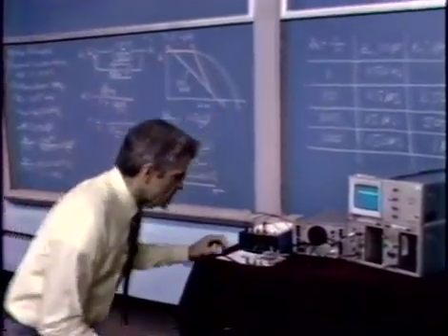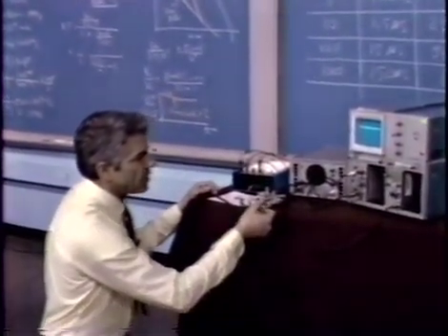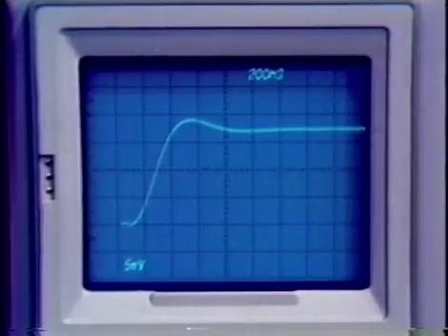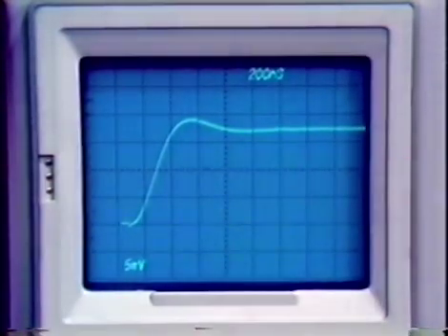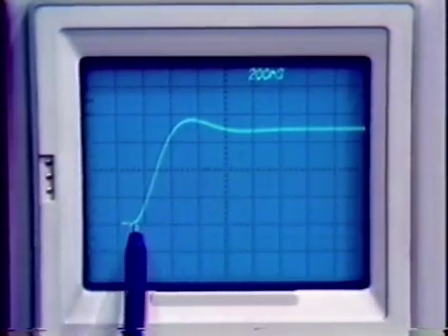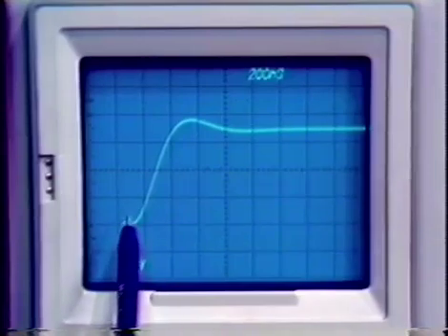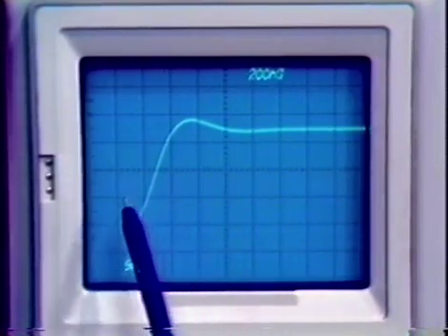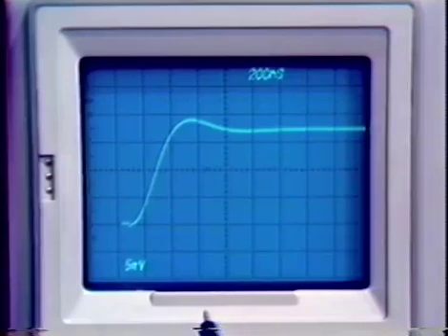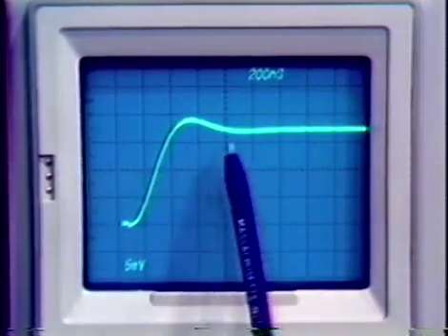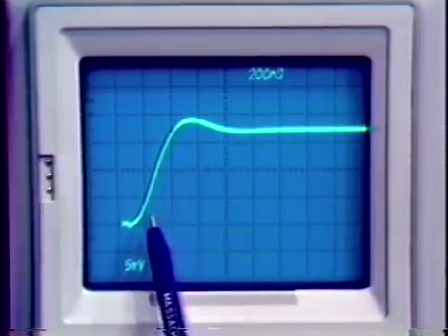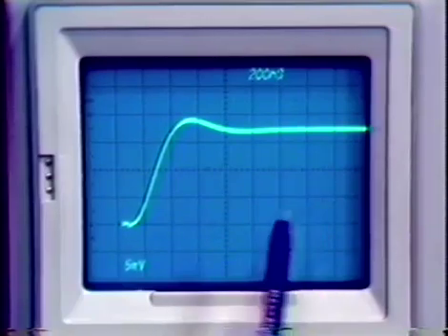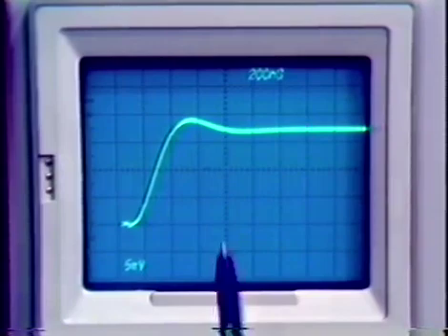We're first going to look at the small signal response of the amplifier. And let's look first at what happens with 1 over s compensation. Here we have removed the resistor in the T network, simply switched it out, open-circuited the resistor, and we get the rise time that we show. We get a rise time in this case of a couple of 100 nanoseconds, 300 nanoseconds, something like that, reflecting roughly a megahertz crossover, reasonably well-damped response.